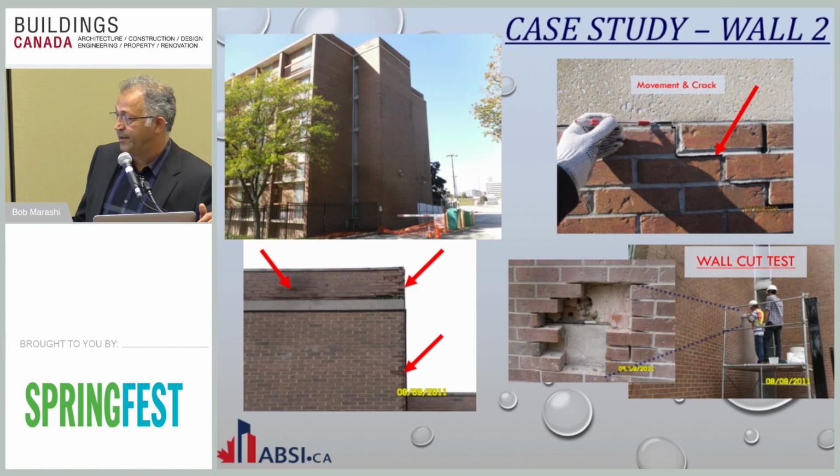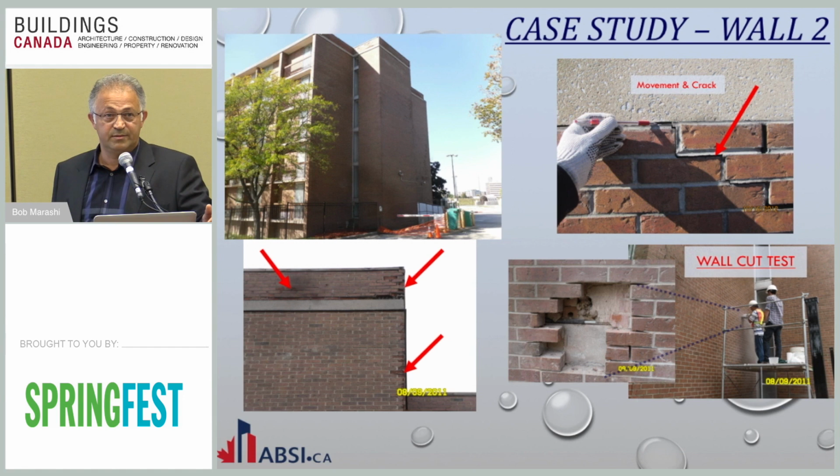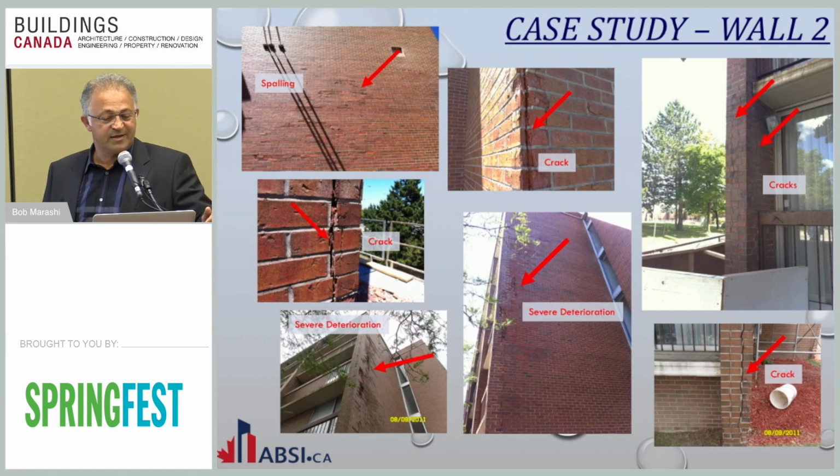We saw a pattern which, unfortunately, you see a lot of times: they use construction garbage and brick to fill up the back of walls. And when you see that, it's bad construction practice. You know there's a problem. So you start opening walls up, and you look at cracks, and you look at behaviors.